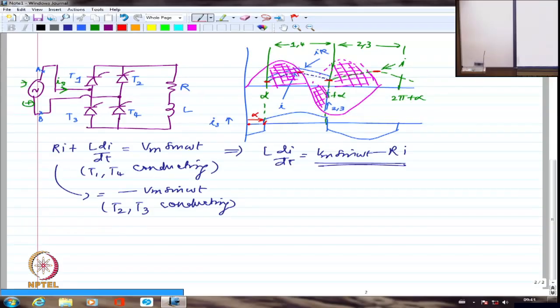No, not at all. Even in the transient, you have to start with thyristor only because you are not changing the circuit. You are starting off with dead position of the circuit. It's dead, completely dead. You are applying a voltage. The current will start from 0. At alpha, whichever alpha it is, at that alpha, the current will start slowly increasing. It is RL circuit, so the current cannot jump. So it will slowly increase.